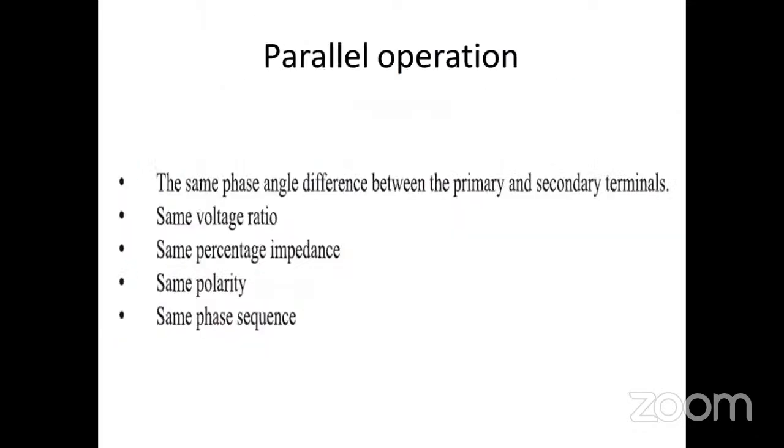Tap changing, parallel operation. This one also, someone asked about the parallel operation. The same phase angle difference between the primary and secondary terminals. Same voltage ratio should be there. Same percentage of impedance. Same polarity. Same phase sequence.